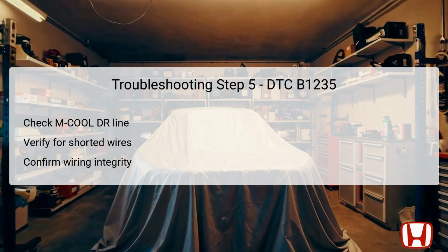If this test returns continuity unexpectedly, it indicates an issue that requires rectification. If continuity is absent, the wire is confirmed to be in proper working condition, paving the way to proceed to the final step of the troubleshooting process.